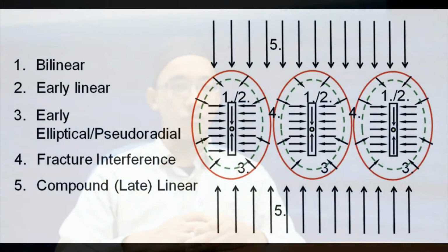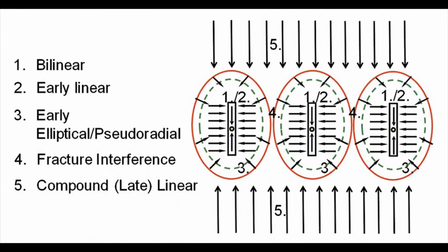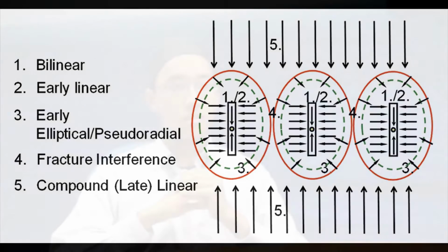There are three basic mechanisms in evaluating pressure transient data from a horizontal well test. The first step: identify the specific flow regimes in the test data. Evaluation of data from a vertical wellbore will generally center on a single flow regime, such as infinite acting radial flow, or what we know as MTR, middle time region. However, a pressure transient test in a horizontal well can involve as many as 5 major and distinct regimes that need to be identified.